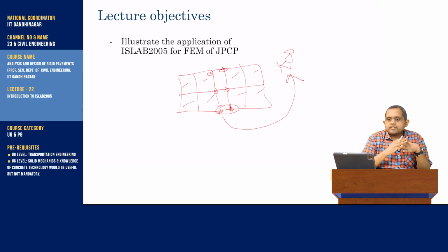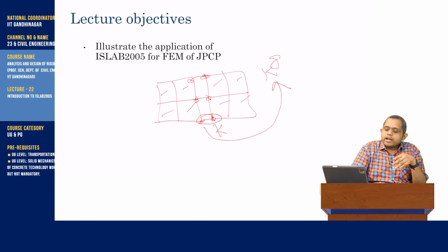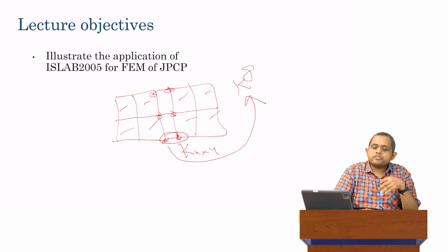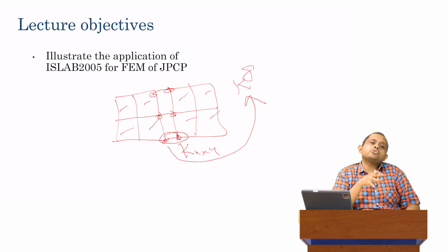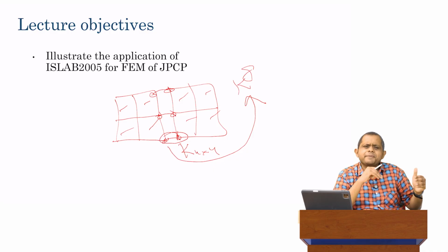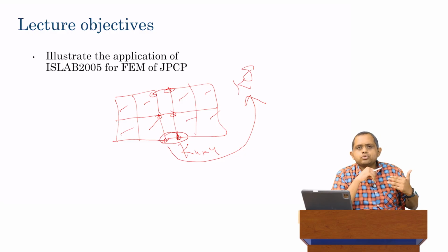So what we saw in the last class was this model. And we saw that this is basically a 4x4 stiffness matrix, which was the component dowel bar model. If you recall from the previous lecture, it was not a very pretty model in the sense that the mathematics was fairly complicated. Now in module 2, not only did I show you all the analytical solutions, I also took time out to show you how to solve the equations. And I pointed out some important things, for example, making sure you use the correct system of units, making sure you understand what numbers to use, not to forget certain roots, so it's not a square root but a fourth root, etc. I gave you those kinds of understandings in module 2.